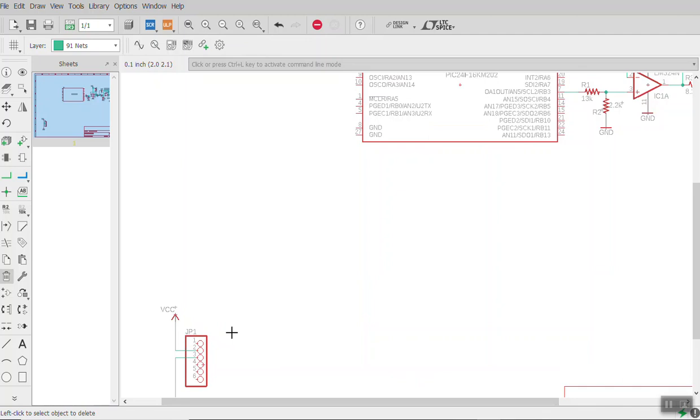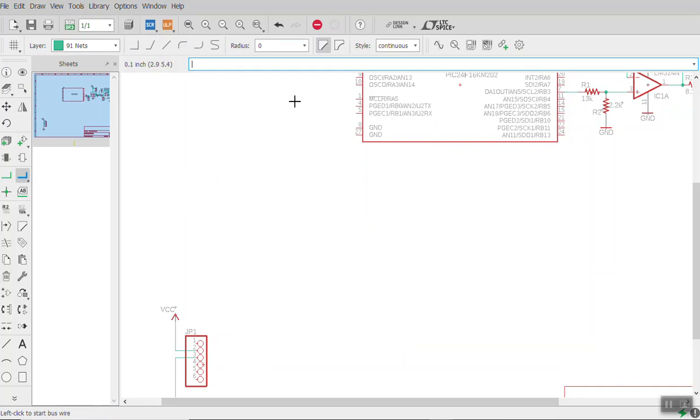When you get to 8 or 16 wires and you're trying to run across a schematic like this, then it becomes a little bit more of a benefit. But let's just see how to do it anyway. First thing is I come over here and select blue, which is for a bus, as opposed to the wire, which is for an individual connection. So I select a bus and I just draw a line that shows where I'm going to be connecting all of the wires. It's a little bit like saying, here's the channel all the wires are going to run through. So I have this bus.